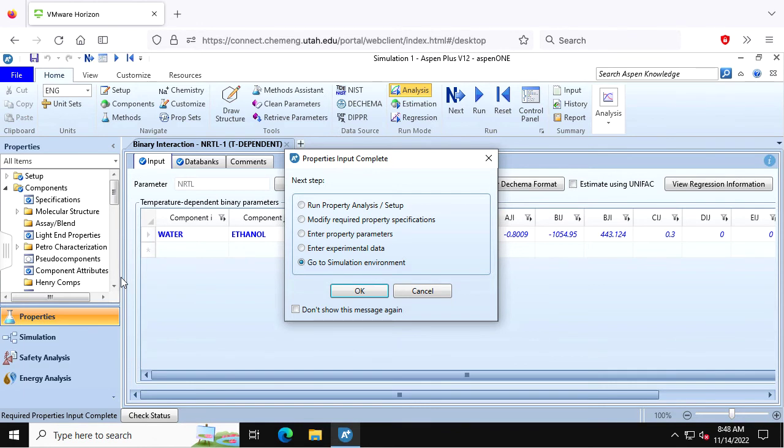If you were doing that in Aspen, Aspen doesn't have one called sewage sludge, and every sewage sludge is going to be different, right? So what you would do is send it in for analysis and get the carbon, hydrogen, oxygen, sulfur, nitrogen, all that kind of stuff, and then maybe also the energy content. There are labs that will analyze that for you. Then you can actually add your own material, and you put in all those properties, and then Aspen can run with that. I'm not going to bother going through that today, but you should know that functionality is there.